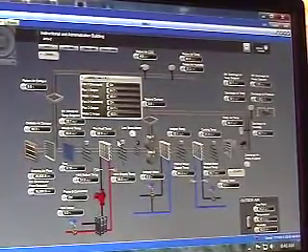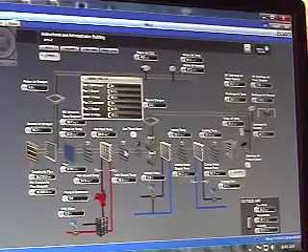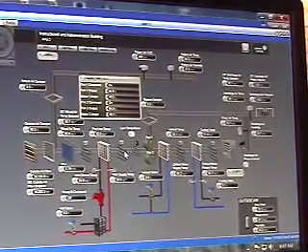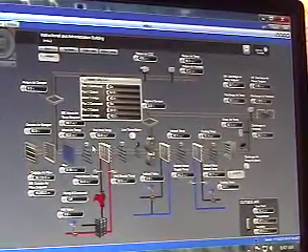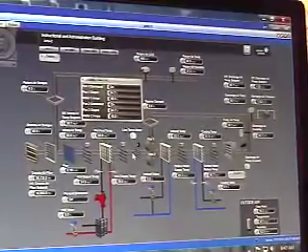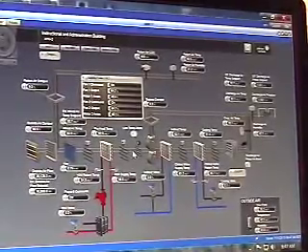This sensor right here isn't used so much for controlling, but it is used as a pre-safety device. If your temperature gets too cold after this coil here, we will automatically override these dampers shut. So we have a low set point, I believe between 44 and 36 degrees, that if our preheat gets below there, we automatically override the dampers the other way, because something's not right if we're getting that cold, just to help prevent the freeze stat from tripping. But it is just a software point, but it is there as a last resort. You might see your dampers going opposite if the sensor gets too cold.